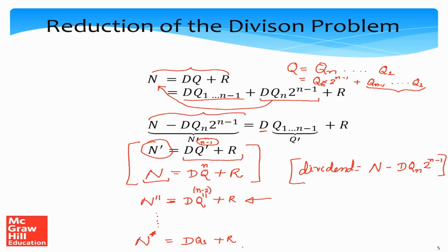Right? Now, at this point, if I have some magical way of figuring out what is the least significant bit of the quotient, then what will ultimately remain is, at the end, we'll only have the remainder left. What's left will be the remainder, and at every point we'll get one bit each in the quotient, starting with the nth bit till the first bit.